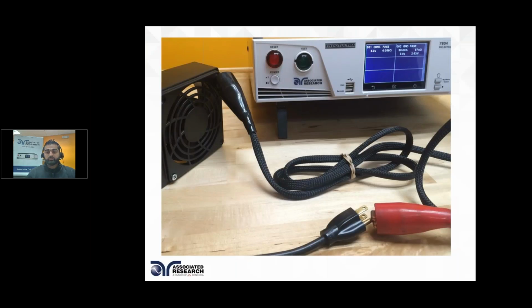Again, here's a close-up view of what we just did. For ground bond and ground continuity, only one part of your circuit is being tested, which is the ground circuit. The red high current lead is injecting high current on your ground pin. The return is taken onto the metal screw or metal accessible point or metal chassis point, and at that point you're performing a ground continuity and ground bond test at the same point. If you look at the results here, you had a continuity test that passed, a 3-second continuity, and then the 30 amp ground bond test that was passed.